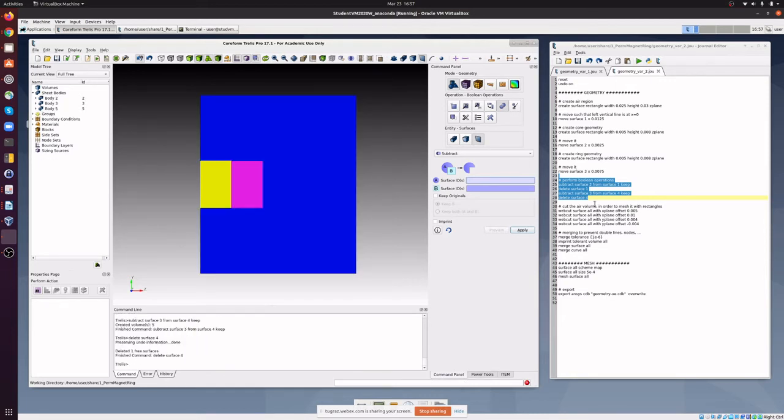In order to perform a hexahedral meshing, in 3D, in 2D we want to mesh it with simple rectangles or quadrilaterals. We need to cut the air volume in Y direction and in X direction, which can be done via these webcut commands.